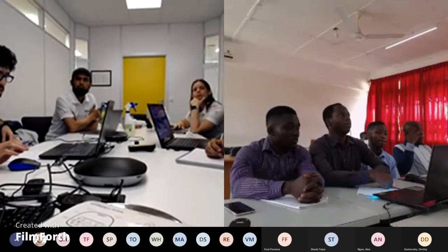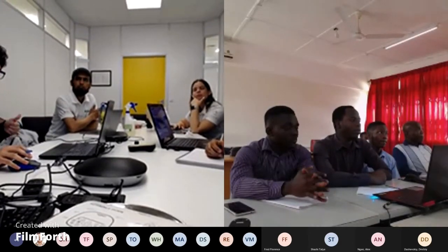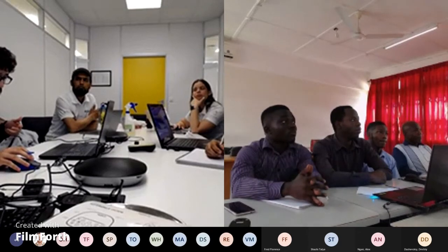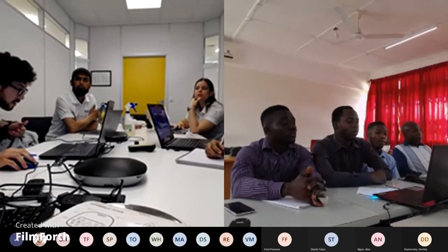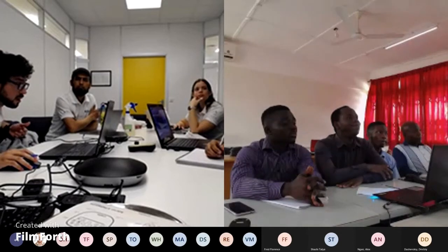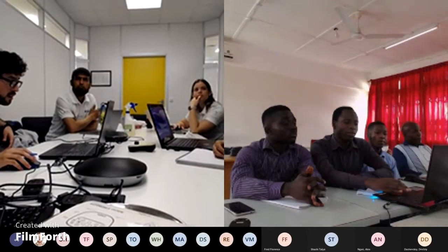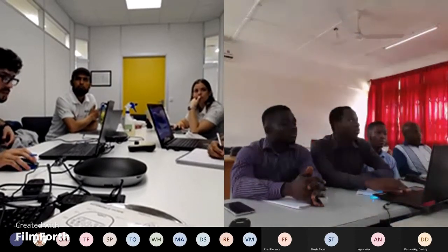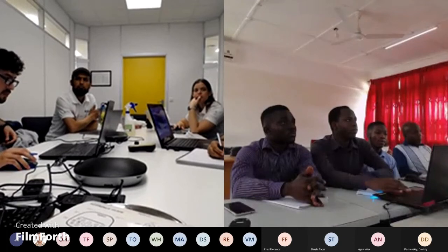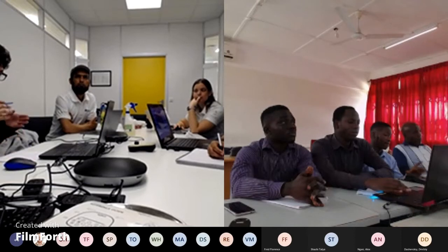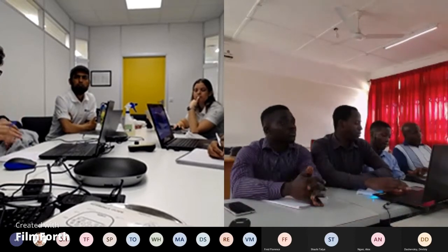Then how are you incorporating randomness and variability in drilling into your model? Right now we are just focusing on 5 parameters: the weight on bit, RPM, the sliding factor, the formation aggressiveness, and the specific energy of the rock. Those parameters are supposed to come from other models, but right now we couldn't integrate too much in that part.